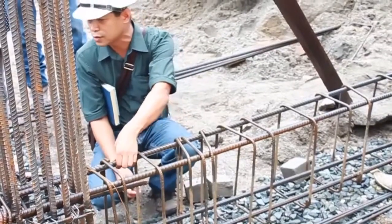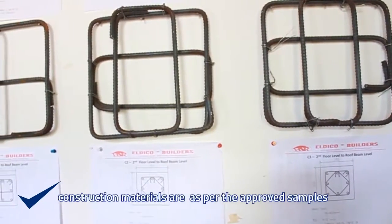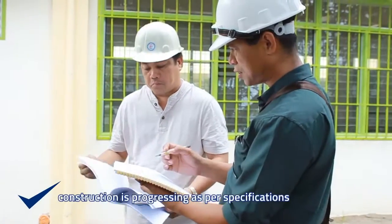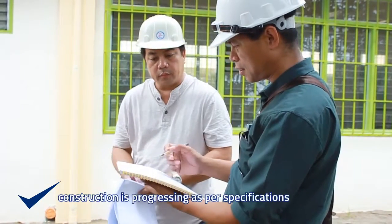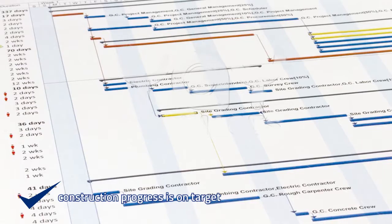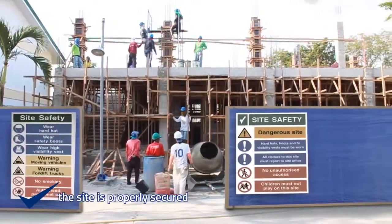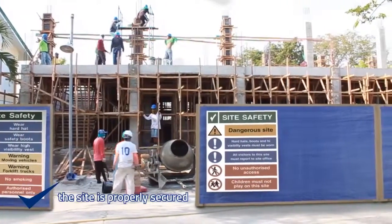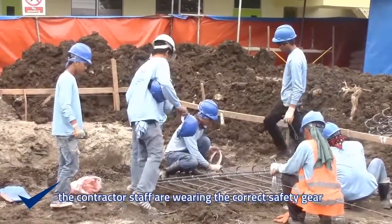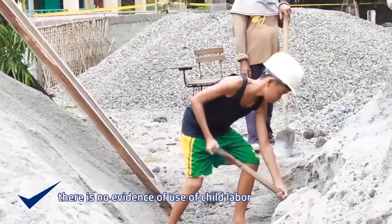At each of the inspection visits, the engineer must check that the construction materials being used are as per the approved samples, that construction is progressing as per the drawing and specifications, that the construction progress is on target as per the planned construction schedule, that the site is properly secured so that there is no access to the site for pupils, that all the contractor staff seen on site are wearing the correct safety gear, and that there is no evidence of use of child labor.